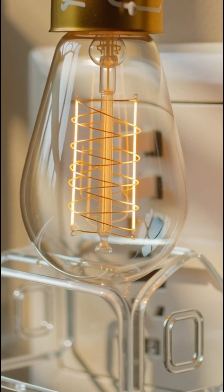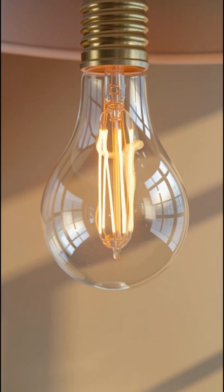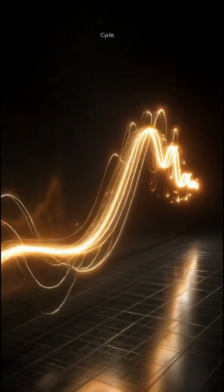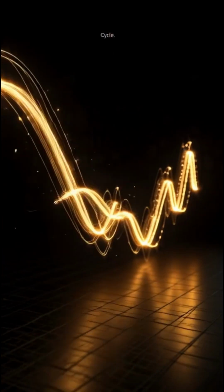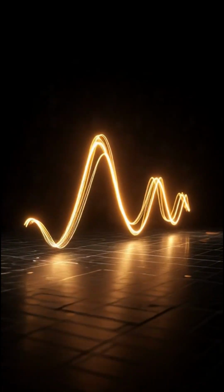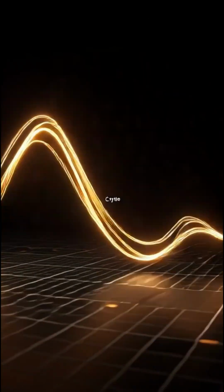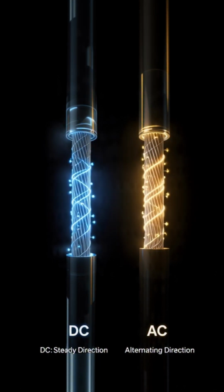One complete rise and fall, positive and negative, is called a cycle. The speed at which these cycles repeat is called frequency, measured in hertz, meaning cycles per second. Depending on where you live, household electricity operates at 50 Hz or 60 Hz. That means the voltage completes 50 or 60 full cycles every second. Believe it or not, an incandescent bulb is technically flickering more than 50 times per second, but the change happens so quickly that our eyes perceive it as steady light.